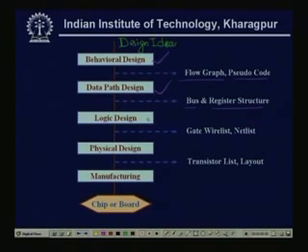And then it is the logic design. So, this is again modular, again I am partitioning into smaller blocks, and these blocks are now synthesized or realized by logic gates, AND, OR, NOT, etc. So, the outputs are a gate wire list, or normally this is called the net list.